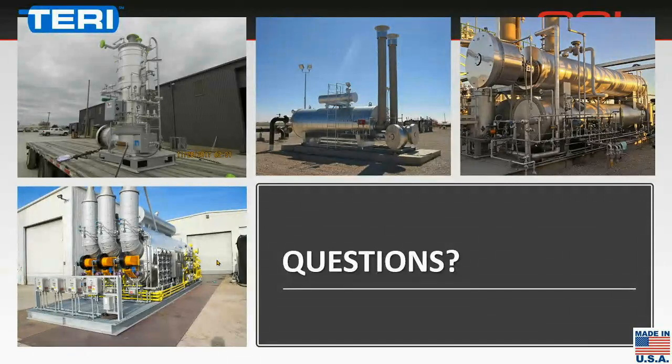So if any of those conditions are met, then it'll send a signal to your SCADA and alert you that something's wrong with the heater. And then, of course, you could go into different types of relighter systems. I know you have everything from the simple push button to more complex relighter and burner management systems, which can control when your burner comes on, when your pilot even comes on and turns off.